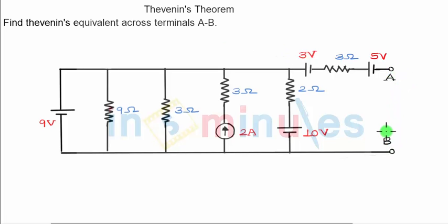There is nothing given between A and B. So in the previous question, we had an 8 ohm resistance here and the question was what is the current through the resistance. So in this case, we will just find VTh, RTh, draw the final circuit between A and B and stop. Whenever such is the case, you can directly start with the first step. As I told you, the steps will be the same. Step 1 will be to find VTh. So we'll first find VTh.